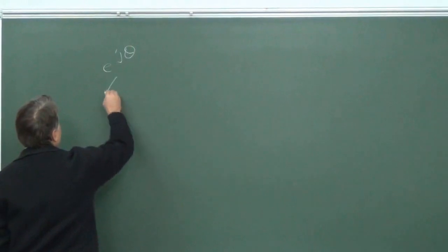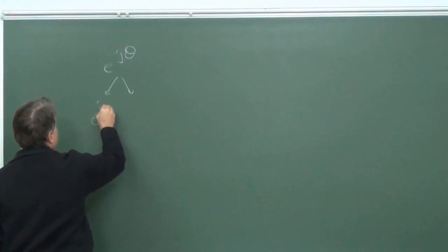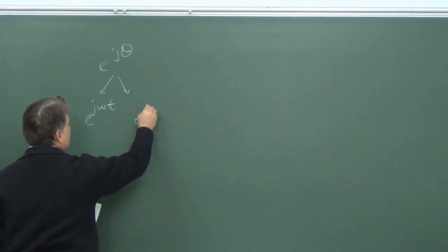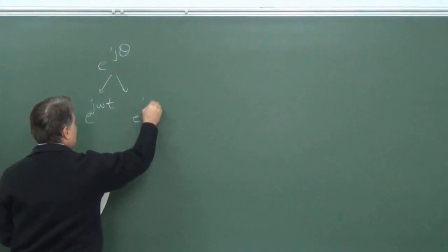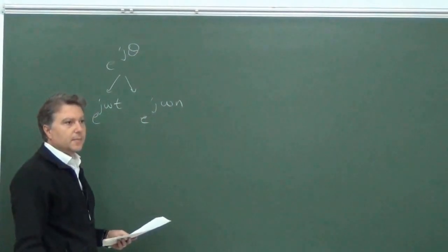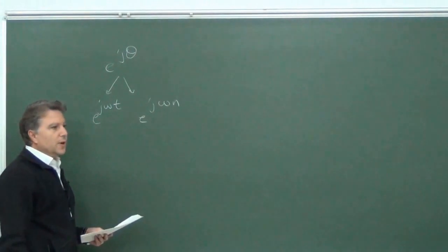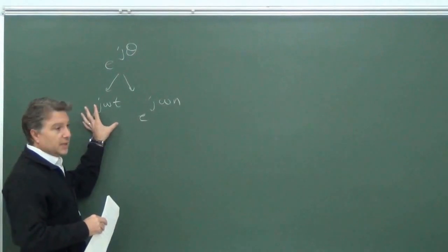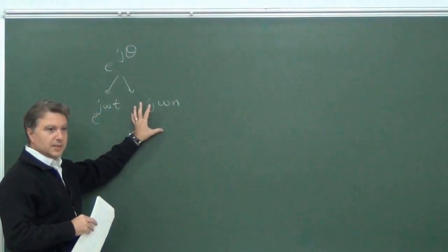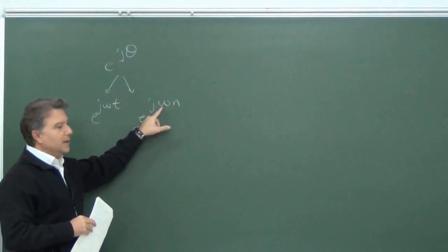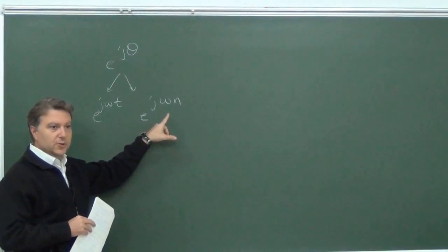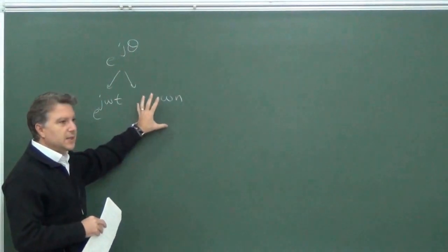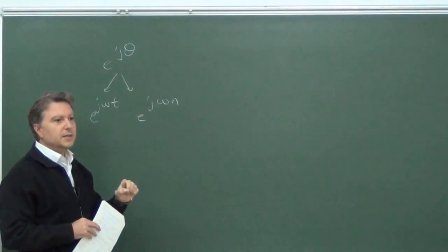And if we are thinking of signals, what you can say is, for example, something like this: e to the j omega t and e to the j omega n. These two are, in many cases, periodic signals. This is certainly a periodic one, but this is, under some circumstances, a periodic thing, depending on the proper definition of a frequency, which corresponds to an integer period. Because we know that for discrete time signals, integer period is necessary.